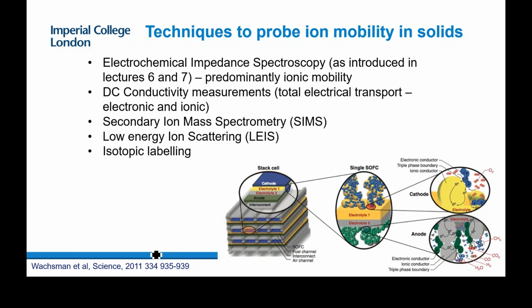So impedance spectroscopy is a really useful technique, because what it will allow you to do is characterize resistance and capacitance, and in the solid state devices you typically get relatively simple, straightforward spectra. So you'll typically have a spectrum which consists of 3 to 4 components. You might have a low frequency component which gives you some information about processes occurring at your electrodes. You probably have a couple of processes which relate to your bulk and grain boundary conductivities. As you go up to high temperatures, as we are with these materials, you tend to lose the capacitive components of those components. So the resistance is then just an ohmic resistance.